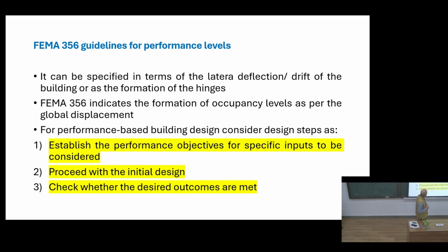A specific case, as Professor Datta mentioned, is a building for which we made the sketch, where plastic hinges formed at the intermediate level also, and sufficient plastic hinges have formed. Then it becomes prone to failure. And as I said, because sufficient plastic hinges are formed, it swings. The load will also move along, additional force will be generated because of that, and it becomes a susceptible region for failure. So in that context, it becomes important.